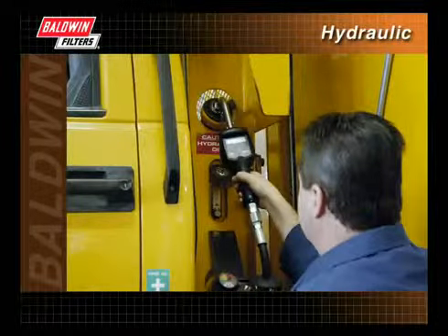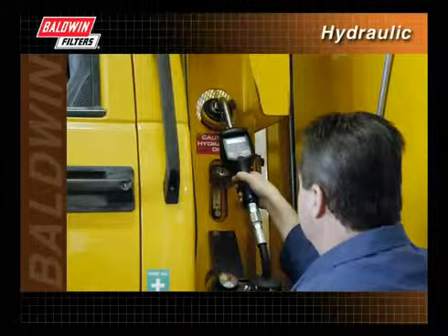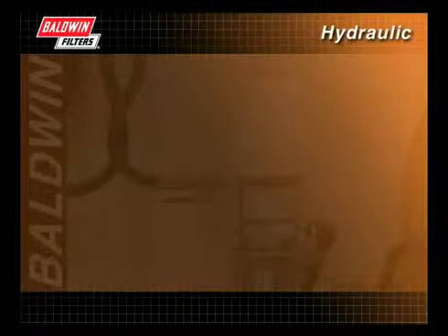Also new, unfiltered hydraulic fluid initially added to the system can be a source of contamination due to cross-contamination and also to the complexity of new additives in the fluids. Pre-filtering of new hydraulic fluid is important to prevent this form of contamination.